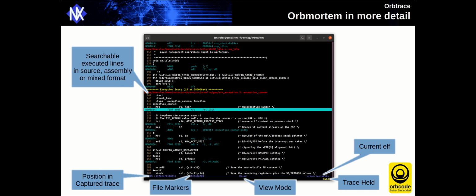And then when a halt occurs, it post-processes that buffer to say this is exactly what was happening when the program stopped. So you get a trace, a post-mortem trace of everything that your program was doing up until the point that it died. Not what you thought it was doing or what your program listing said it was doing, but what it actually did, the specific instructions in real time that it executed. Now you can imagine how useful that is.